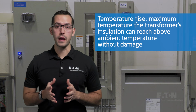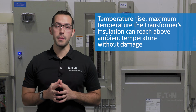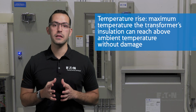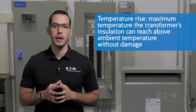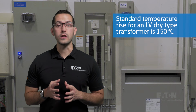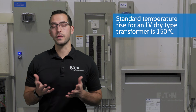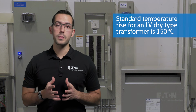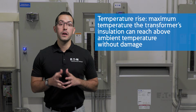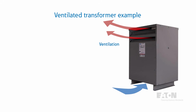Temperature rise in a transformer refers to the maximum temperature that the transformer's internal insulation can reach above the ambient temperature during normal operation. The standard temperature rise for a low voltage dry type transformer is 150 C, or 150 Celsius. There are other optional temperature rise values available, with the most common options being 115 C or 80 C. To understand temperature rise a bit more, let's look at a ventilated transformer example.